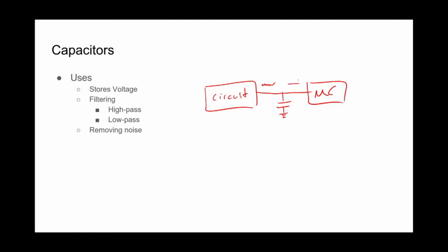So essentially what's happening is we assume that there's some inherent resistance in here, right? I guess I should draw it. So there's some resistance in that circuit, or even just in the wire itself. And when you compare that with this capacitor here, this is actually our low pass filter. So the lower frequencies, the signals we're trying to measure, are able to pass through, while the higher frequencies, the noise, are filtered out. Not the resistor, sorry, that's R, that's a resistor, that's a capacitor. The noise right there is filtered out in our low pass filter.